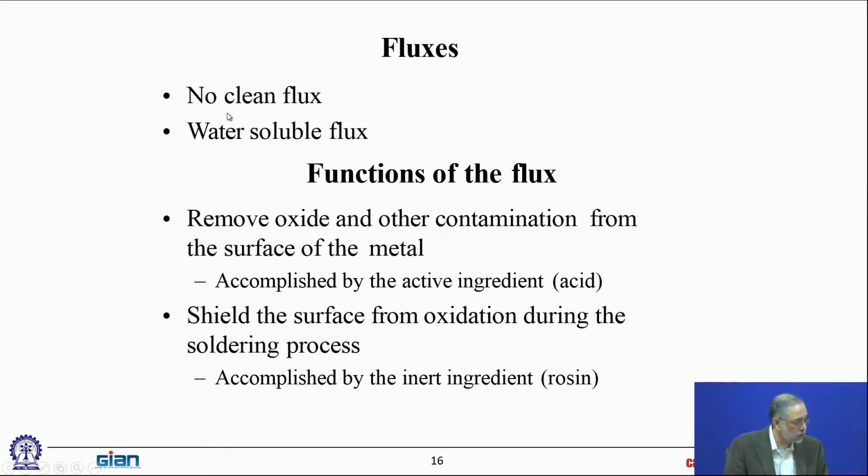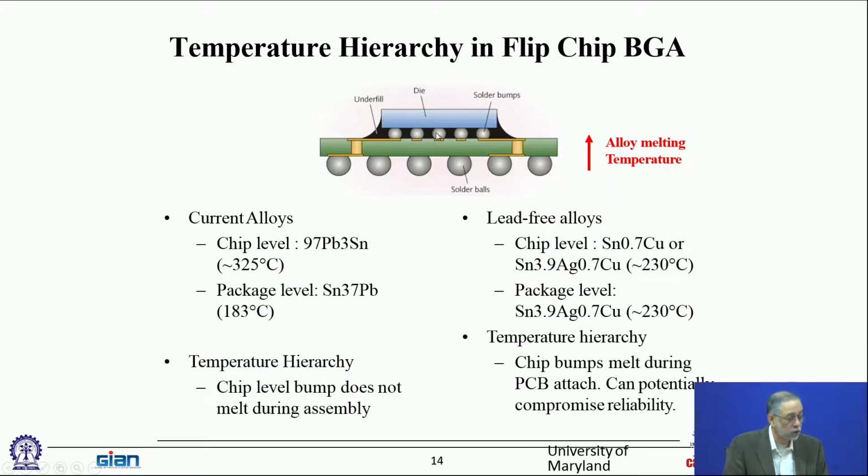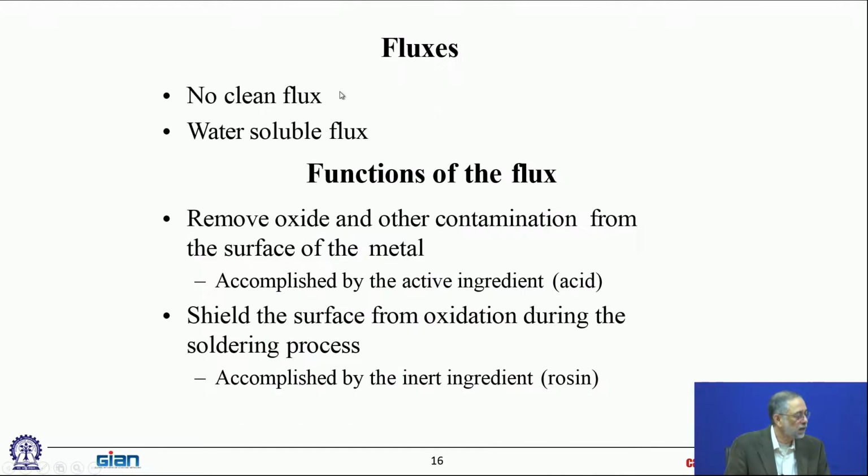And then in places where you cannot clean them, so for example, that flip chip joint would be hard to clean, very little clearance. And now we are talking about micro bump joints, which are much, much thinner. These would be about 50 to 60 microns high. Micro bumps would be barely 20 microns high. So especially when you're doing die-to-die stacking, direct stacking, those are micro bumps with very little clearance, almost impossible to clean those. So for that you have low residue fluxes. So fluxes basically have volatiles. The volatiles will evaporate and you're left behind with solid residues. That's why you need the water cleaning. The water soluble ones need cleaning, and the low residue ones, specially formulated for low residues, are not cleaned.